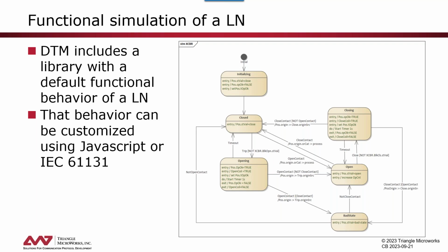Okay, I was muted, sorry. From the 61850 perspective, there is no requirement for how you create your ID name. The ID name can be completely configured in SCL. So it's a configuration element that we have to design to determine when we build the system. Yes, there is a recommendation in the standard that you mentioned that could be used, but it's not mandated. About the names, I think there are more than 6 characters allowed.